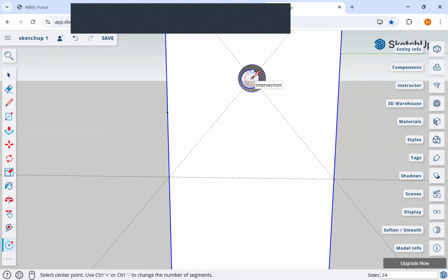Now, I go to the intersection here. Because I want to draw a circle perpendicular to the red axis, okay, the circle shown here must be red. It cannot be any other color. Okay, cannot be a black. If it orientates to the curve, then it's actually a black circle. So to the center of component, click and I move it out. Once I move out to anywhere on the circumference, it's actually 2 mm away. I click. So I've drawn a circle.